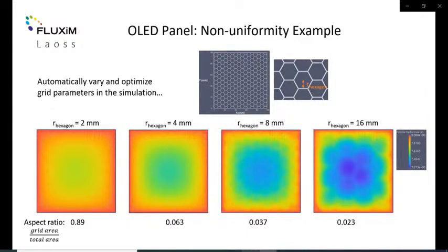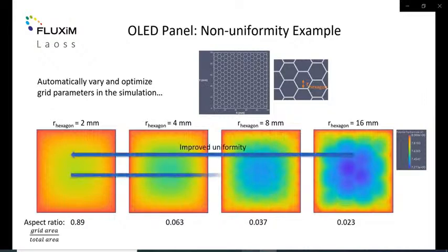Here we show the potential distribution for a varied hexagon radius with decreasing radius. We clearly see a much more homogeneous potential distribution, which would lead to improved uniform emission. However, the metal grid is non-transparent. It also has some shading effect. This will increase with decreasing radius and could lead to lower emission in total. The simulations now allow us to find the optimal configuration of the electrode.